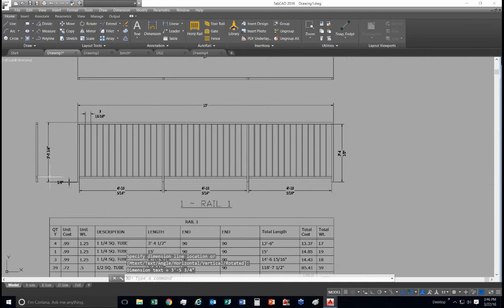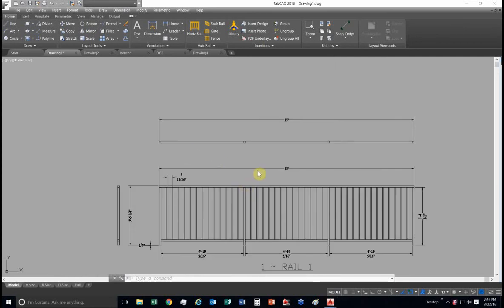A lot of times you'll be a half inch off because the old dimension command would pick the endpoint of the dimension line. Now it does not recognize it. But if you need to use a dimension as a reference, it will recognize the midpoint, but not the endpoint.